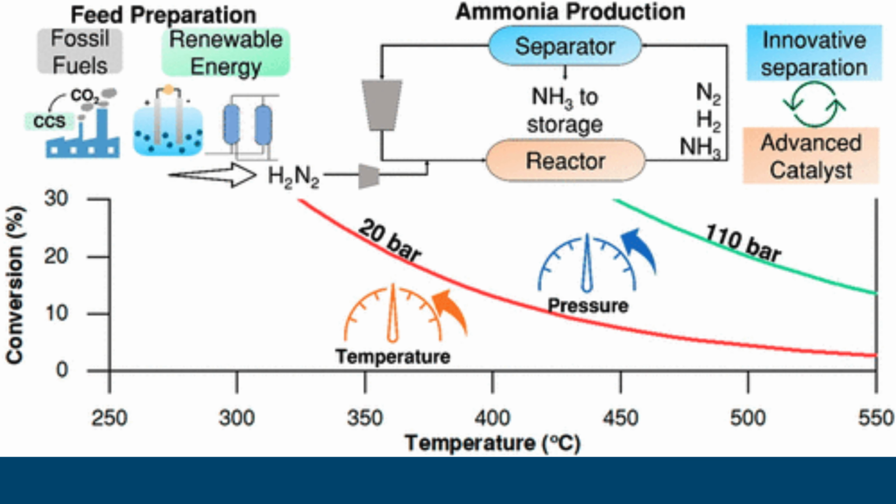Traditional ammonia separation relies on condensation at high pressure, which inherently favors operation at elevated pressures. Innovative approaches, such as absorption-based separation using metal halides or other solid sorbents, have been proposed to enable efficient ammonia removal at lower partial pressures. These developments could facilitate the design of modular, small-scale Haber-Bosch systems suitable for distributed production, particularly in regions with abundant but intermittent renewable energy resources.